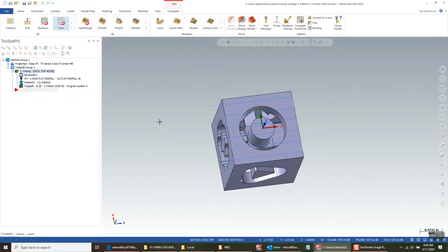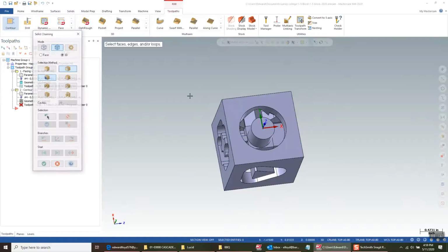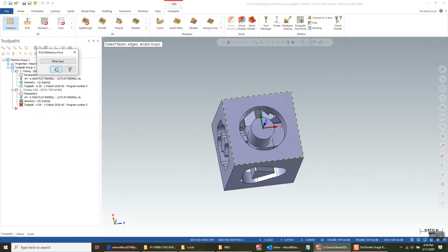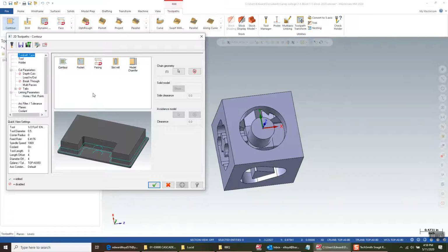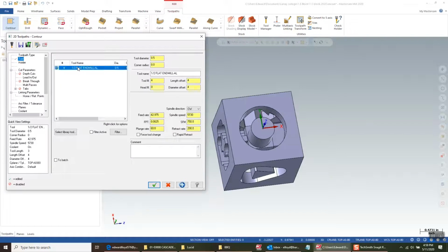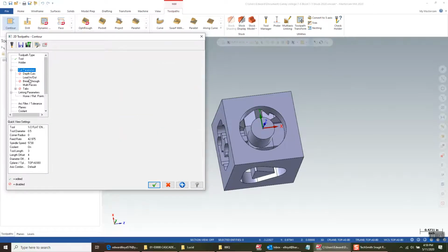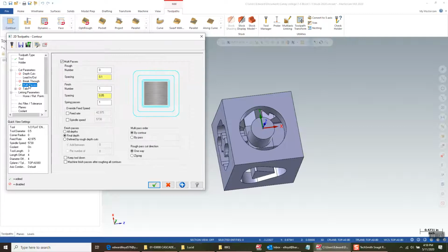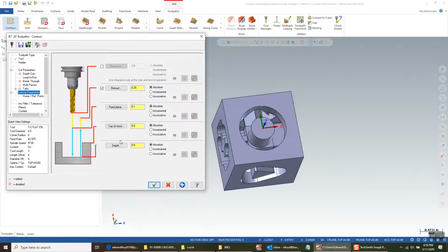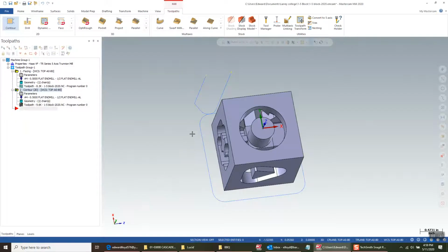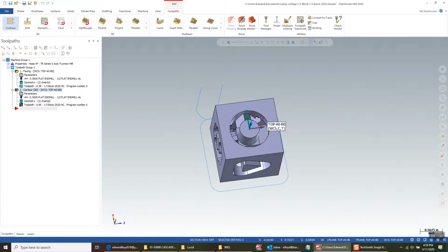Just a quick little facing toolpath. Then I'll go ahead and just contour the outside perimeter. Same tool. All this stuff is just kind of my default setup. So my linking is going to be -1.5 inches. Alright, so we faced it, did the outside profile.